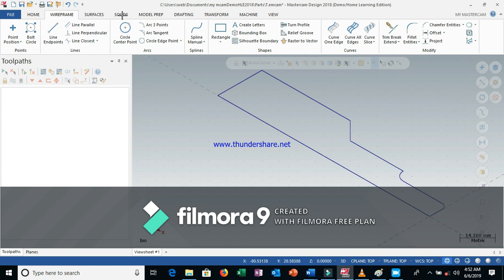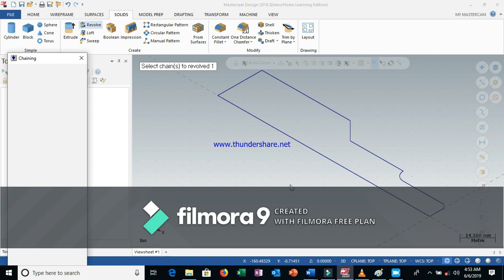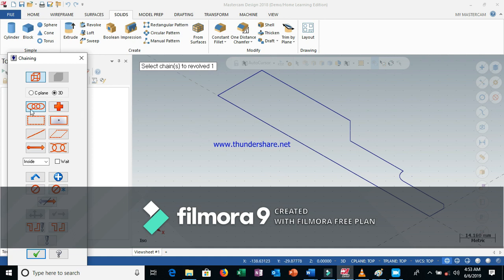You know which command will make the rotary parts in 3D, that is revolving along the axis. Go to solid, go to revolve. Yes, you will get the revolving in the form of a chain. Okay, just select this chain.